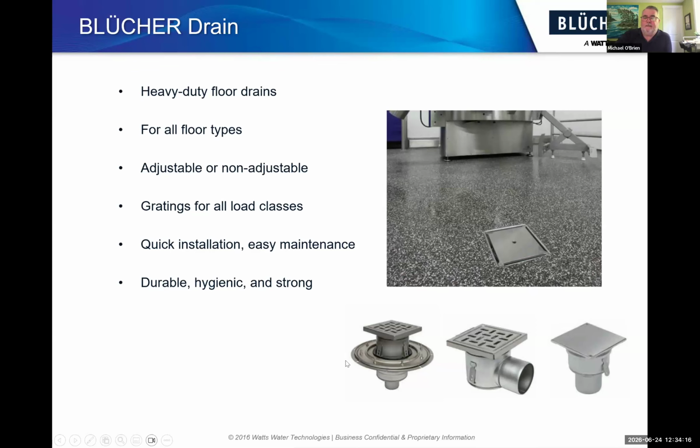Any water that gets onto that through a crack in mortar, for instance, in a tile floor or anywhere else, will eventually make its way towards the drain and then weep through the holes here down into the P trap and out. So if you have an above grade application, quite often that's what you want to be specifying.